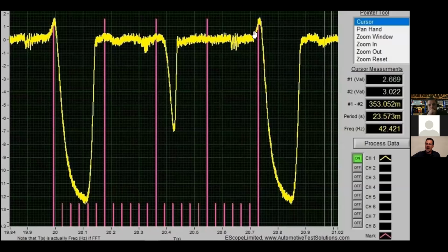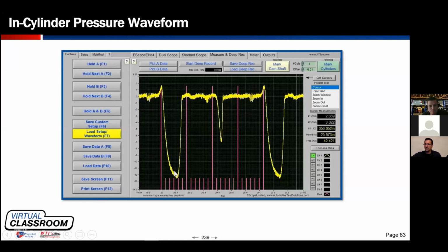And on top of that, if I had a hole in this combustion chamber, right, if I have a bent valve and it won't seal, am I going to pull minus 13 psi, 24, 25 inches of vacuum in the cylinder? Am I going to pull a vacuum if I've got a hole in there? There's no way in heck that's going to happen. So now I'm getting excited. I think I'm onto something here. Maybe this isn't as bad as I think. So we're going to pursue it further.